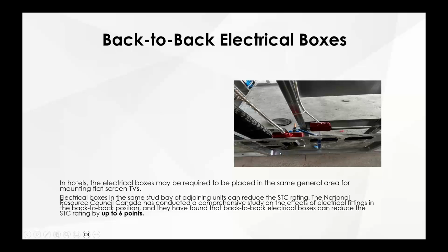I know you've got a reputable sound consultant on this job. And they said, oh, yeah, they came out and they already gave a fix. They wanted us to add drywall on the inside from here to here, stud to stud, 24 inches down and past. Now, I thought that's great because the third-party consultant got involved in there. And this is what I would recommend right now, right here.